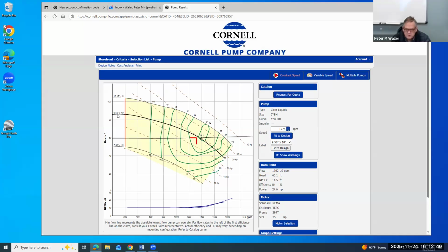So this is our pump curve with a 9.5-inch impeller. So again, these pump curves are for certain impeller diameters. This is the 9.5-inch impeller diameter. These dashed lines are the horsepower lines. So you always have to be under the horsepower line. Let's say you had a pump curve that went above the horsepower line out here.